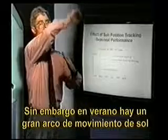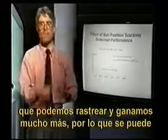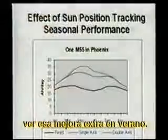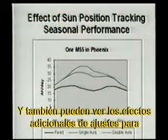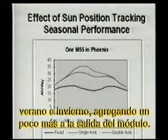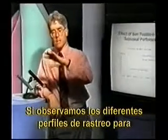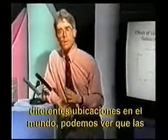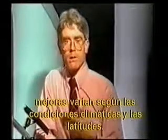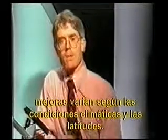In the summer, however, we have a large arc of sun movement that we can track, so we gain a lot more. So you see that extra enhancement in the summer. And you also see the added effect of adjustment for summer and winter, adding a little bit more to the output of the module. We can look at different tracking profiles for different locations around the world and see that the enhancements are slightly different depending again on particular weather conditions and particular latitudes.